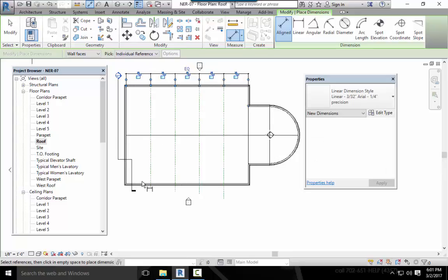And what's that going to do for me? Do I want things equally spaced when I'm talking about where I'm going to put my roof drains? Yeah, the more equally spaced, the more the stuff can be the same. The roof drain sizes can be the same. How I deal with it can be the same.